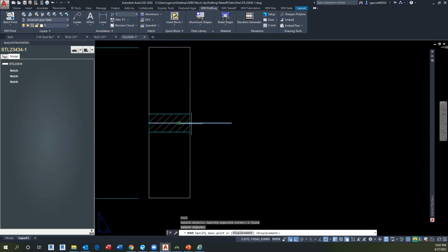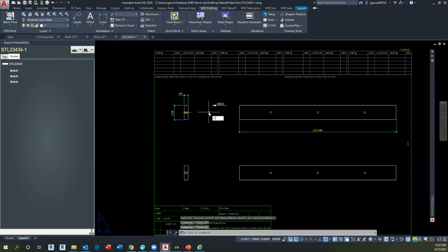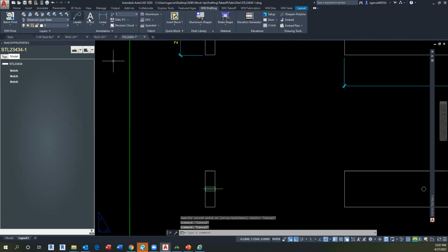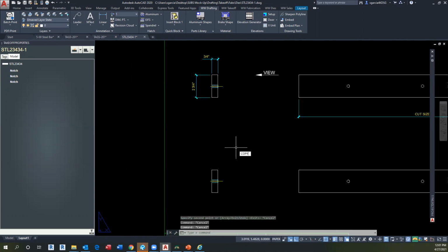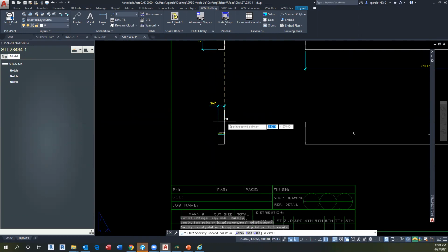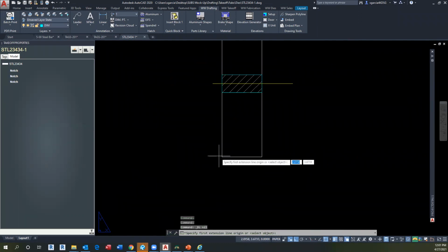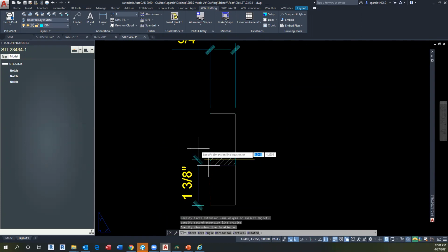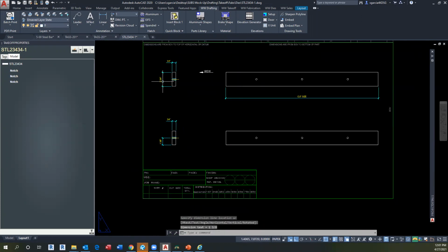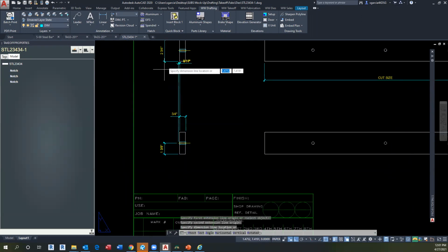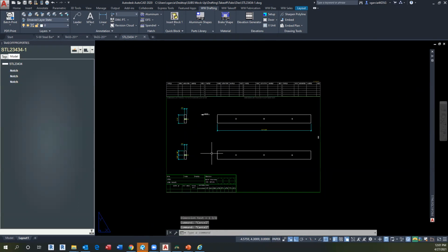If I go here and then center it, and then I copied that one. I can copy that one to here and copy there. There you go. So in this case, I don't have a counterbore hole, so I can recycle this dimension. It's exactly the same because it's passed through. But I have a center line, which is good for me because that's what I'm going to use as a reference. Center line there. And I use this line to use the same direction. And again, 138, and I use that one direction to center it, and I have my dimension.